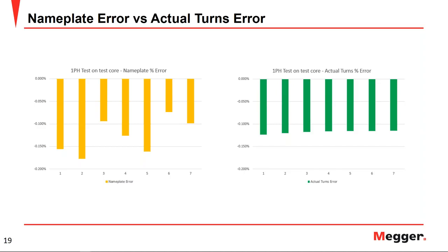So there is no compensation, just a measurement of all the different positions, and then you compare to the corresponding position from the voltage table or the nameplate, and then you can calculate your errors for each of the positions of the tap changer.